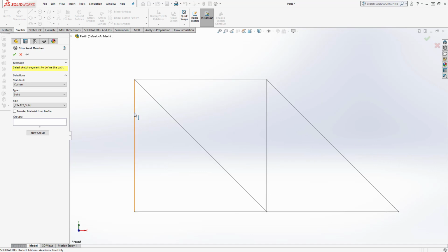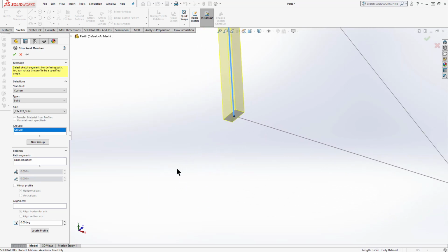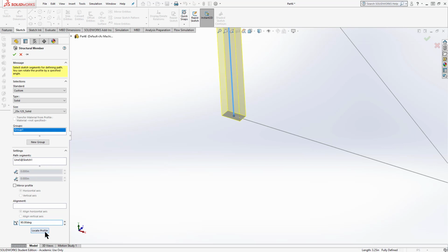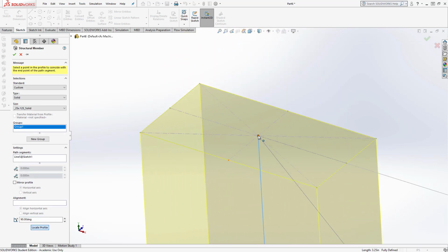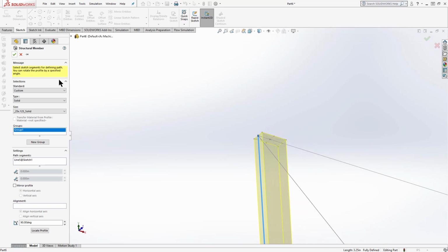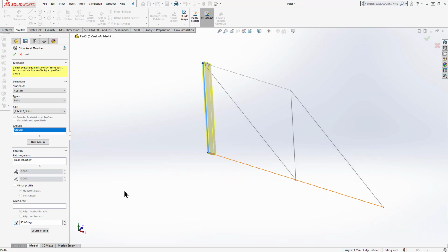We're going to start over here on the left-hand side and drop the piece on. Let's look closely at it. You'll notice that it's oriented 90 degrees off. So the first thing I'm going to do is correct my orientation by 90 degrees. The second thing I'm going to do is locate the profile. Now you'll see that profile is drawn so that I can locate it on any edge or any center edge. I'm going to choose this edge over here, and that keeps the entire body of the structural element within the size of the truss itself that we've drawn. So there's the first piece.